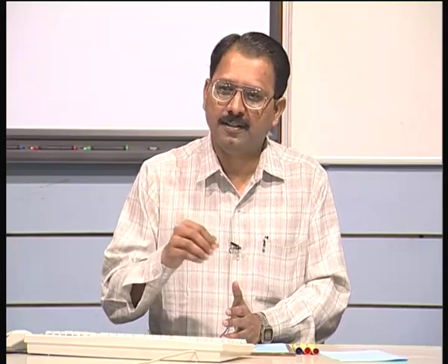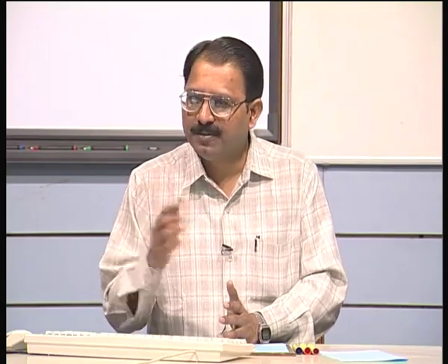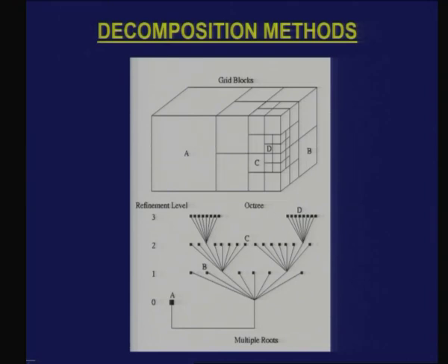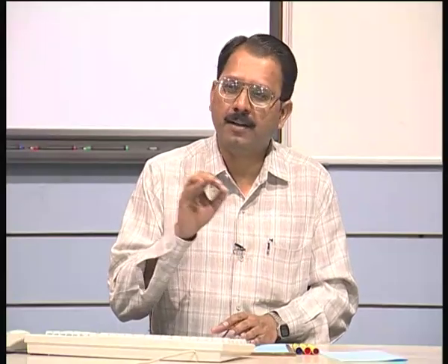I will say that there is a cube which is completely filled, but if it is partially filled, I will further subdivide it into smaller cubes. So when do you go for a subdivision of a cube? First, given a cube, I divide it into 8, and I will check; there are 3 cases. If a cube is completely filled with a material, no further subdivision. If a cube is completely empty, there is no material, no further subdivision.